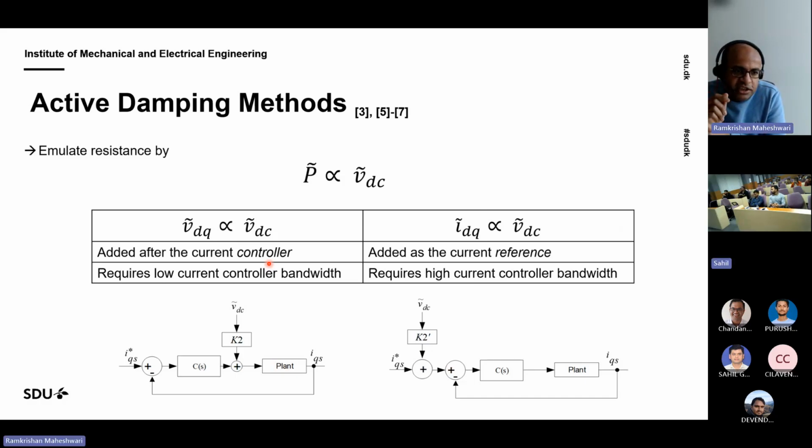Yes, but if we talk about sampling delay, from sensor to the microcontroller, you will have a couple of nanoseconds or a couple of microsecond delay, right? Yes, sir. I don't think any controller can take care of that. You have to have a very high bandwidth controller to take care of those effects. So all these things are happening at 300 hertz or something like that, so I don't think it will be affected by those things. And we haven't seen that in experiments as well. Okay, sir. Thank you, sir.